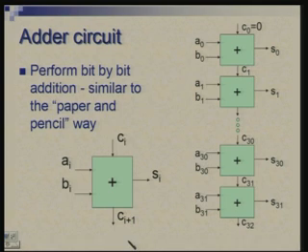In this you would notice that C 1, which is the carry out of the first unit, is dependent upon C 0, and C 2 is dependent upon C 1, and so on. So, it is this dependence of carry from one stage to another which has to be taken into account to complete the operation, and our attention would be focused on this particular aspect of carry going from one end to the other end, from the LSB side to the MSB side.